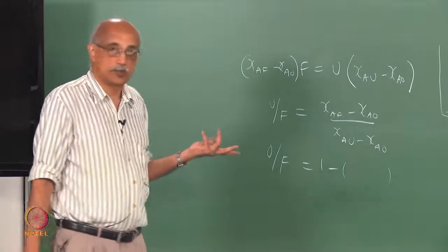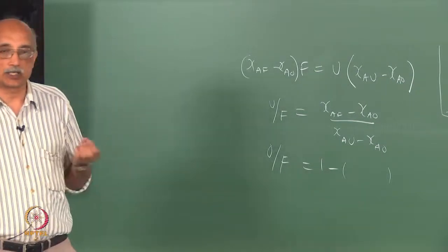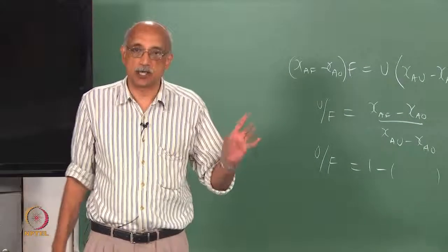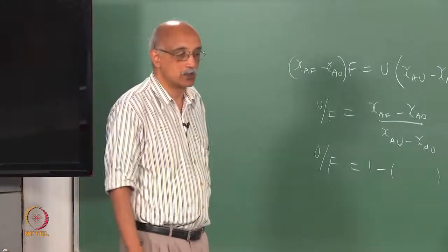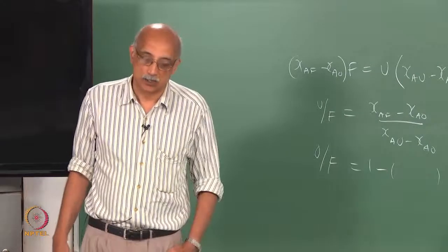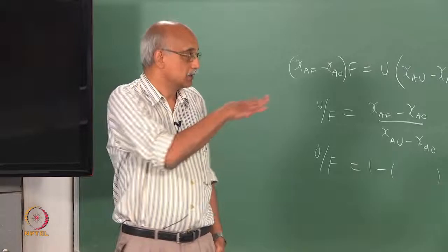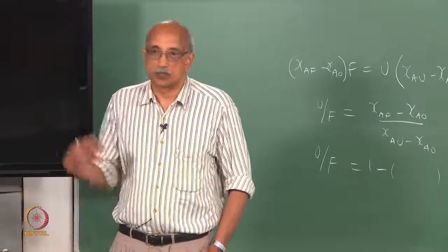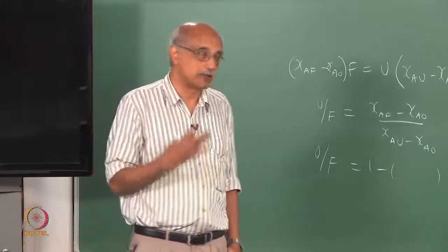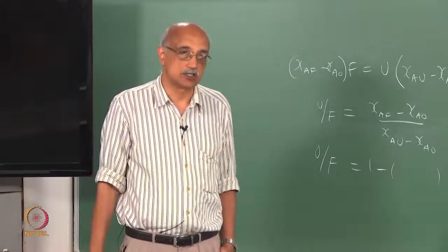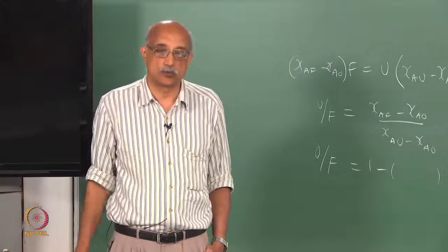Ideally E should be equal to 1, but you will see that when you actually do the calculation, depending on how the split happens, you may get a value that is close to 1 or not. So, that is screen effectiveness. This is one of the problems you will work out in the tutorial. You will be given certain numbers, and you have to be able to calculate screen effectiveness based on the measurements on the feed, the underflow and the overflow.